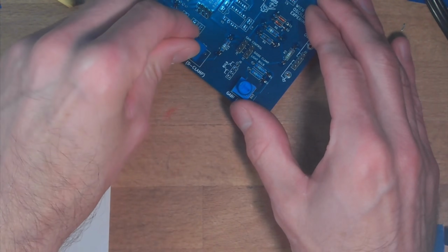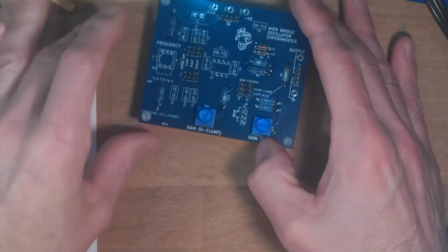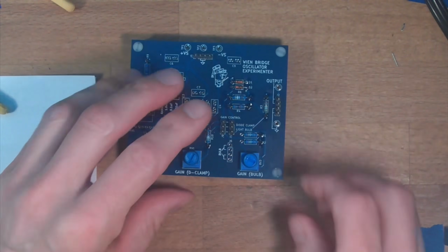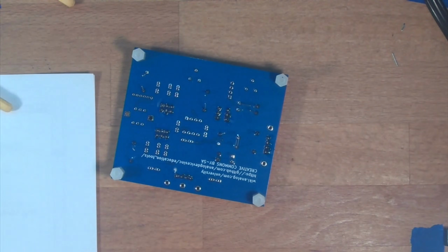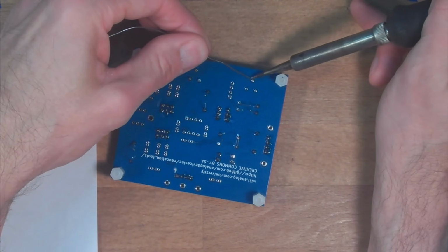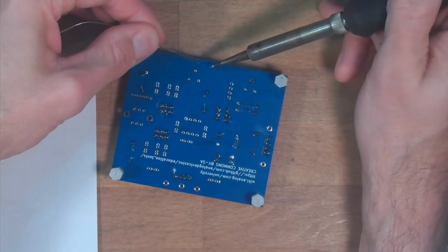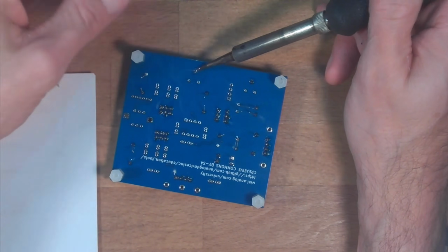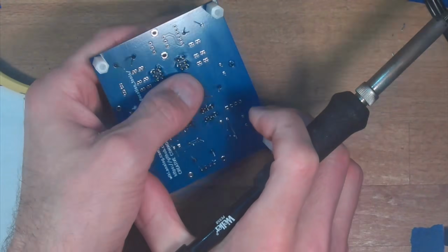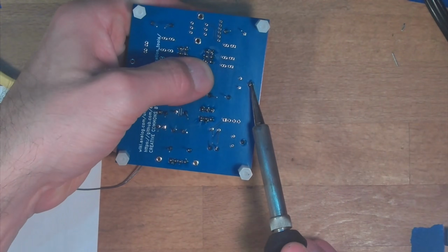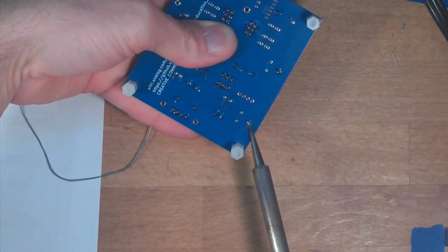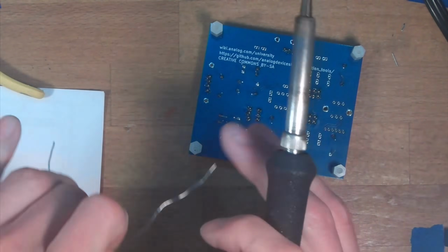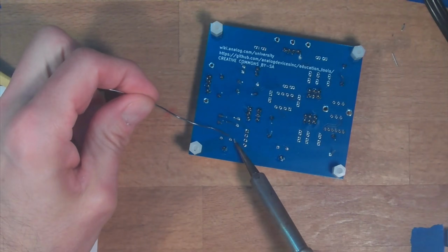And we're going to get this little guy in here. Okay, and then I'm just going to kind of wing it here. So let's see if we can set this guy down. Yep, good deal. And then what I like to do is tack one wire down. Okay, and then lift the board up, press from behind, give it a little reflow. Same on the other pot, give it a little reflow. Okay, great. Now you know that they're flush and you can hit the other leads.